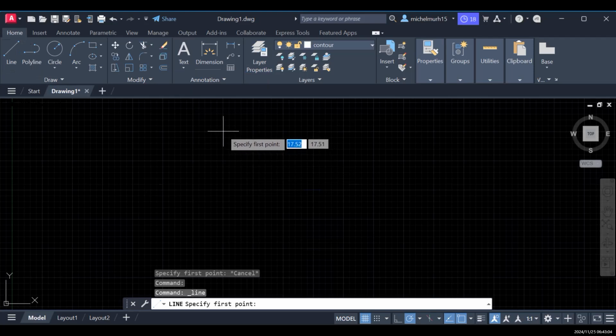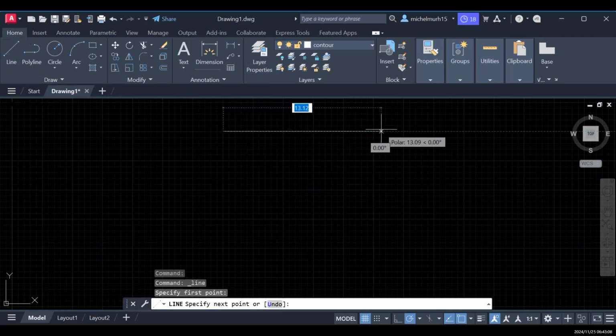So the touch line is the horizontal line. I'm gonna use this horizontal line, and it says 12. So I'm gonna just click on 12, right? And it should be 0 degrees. If I wanna change the degrees at the same time, I can change the degree also. Okay, so it's 12, 0 degree. So it should be a horizontal line.